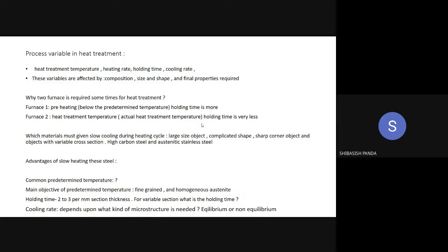If you do that, sometimes what happens, it will generate some cracks, thermal shock. Understood the point? Thermal shock will be there, because a sudden temperature gradient will be created. So that it will lead to thermal shocks. It can generate some defects, cracks in the material. So do not do that, basically.